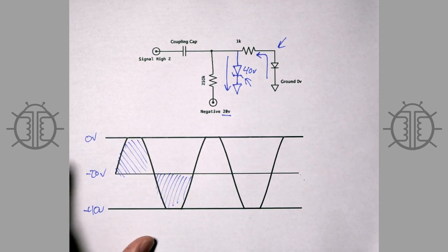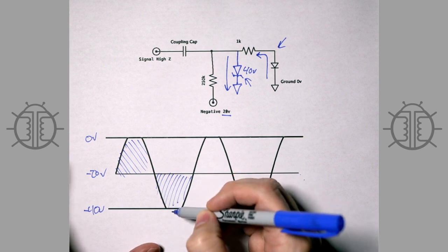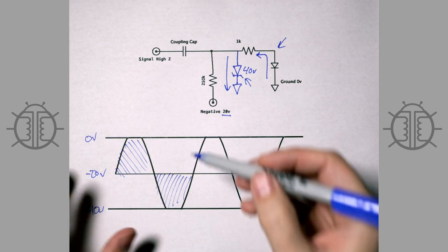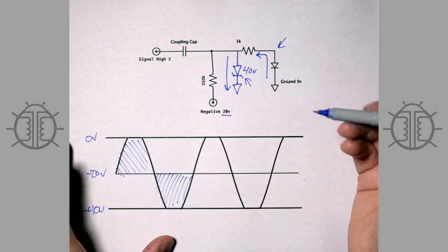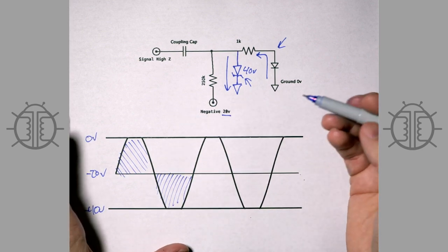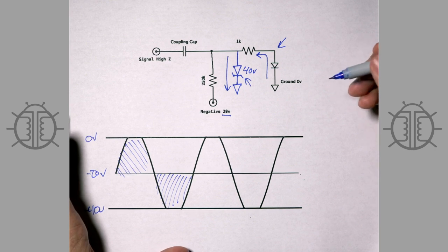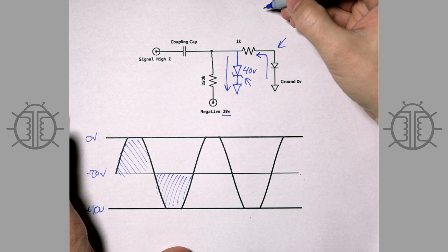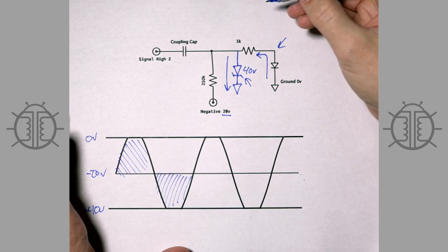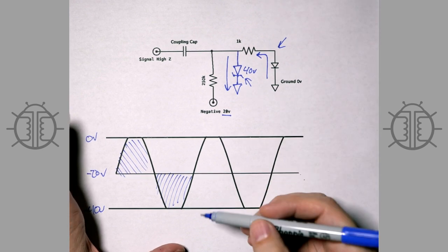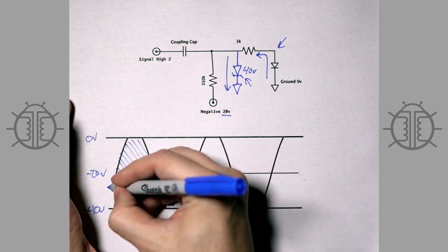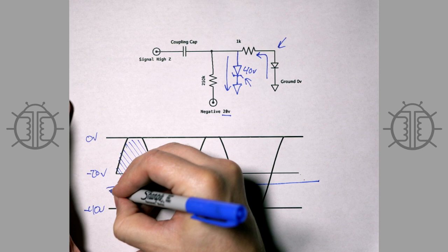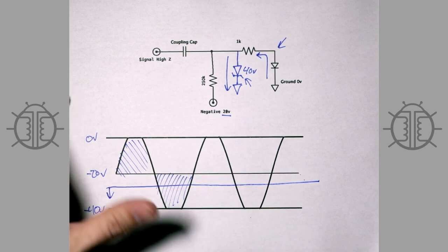But as you can see, this does actually fix the problem. Another thing I should mention is you might think, oh, isn't it going to cause more distortion adding extra clipping to the signal waveform? And the answer for that is no. One, the output waveform is already clipping. You've reached 0 volts in your AB1 output stage, and so you're visibly clipping on the scope already. Also, it's good to remember that below a certain point here, your tube is off.